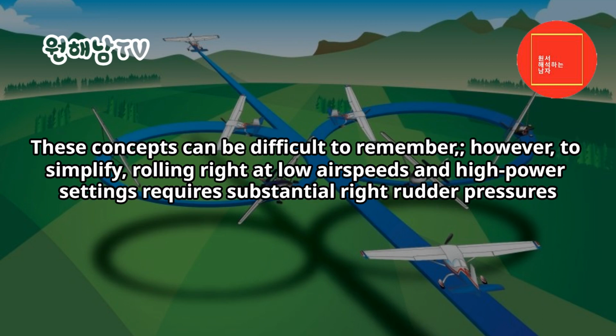These concepts can be difficult to remember. However, to simplify, rolling right at low airspeeds and high power settings requires substantial right rudder pressures.